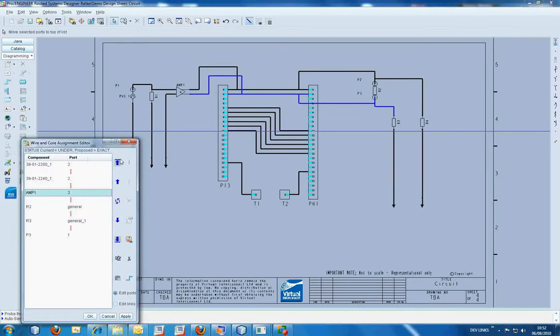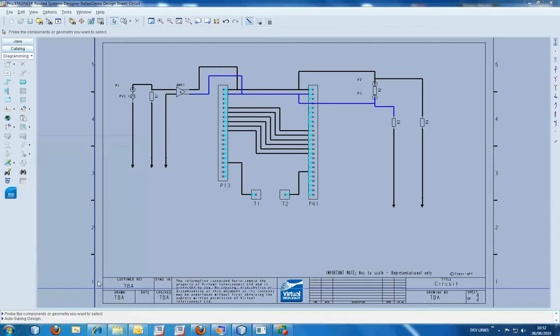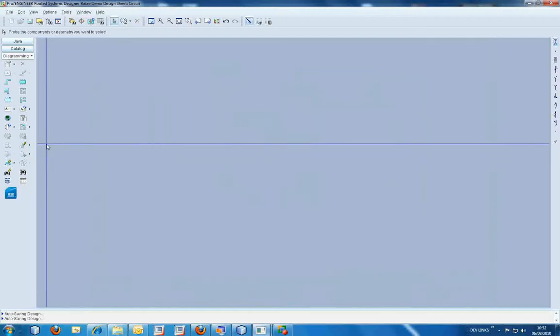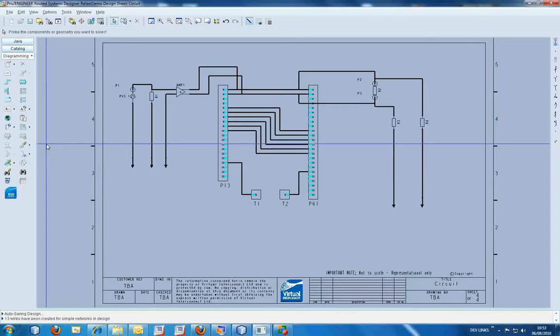So if we do this for the final signal network, we'll have defined all of the wires that the signal networks will make up, and for the remaining wires in this circuit sheet we can use the auto wire assignment to process all of the remaining wires.